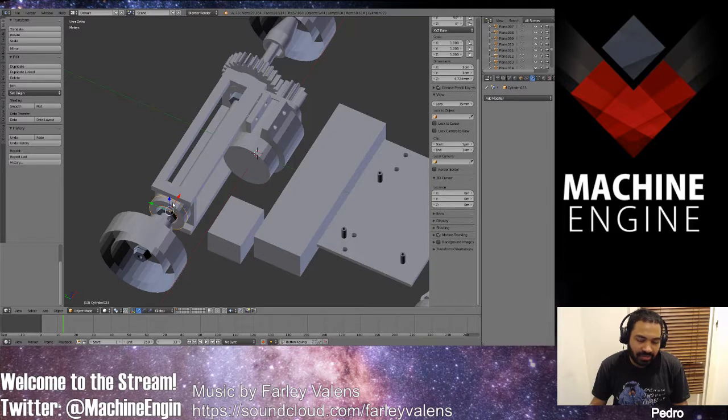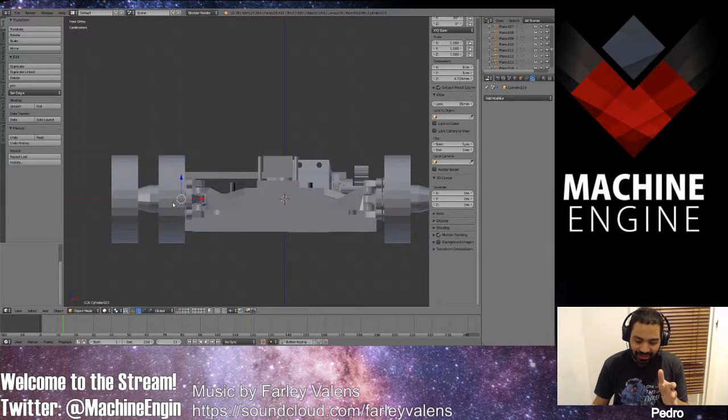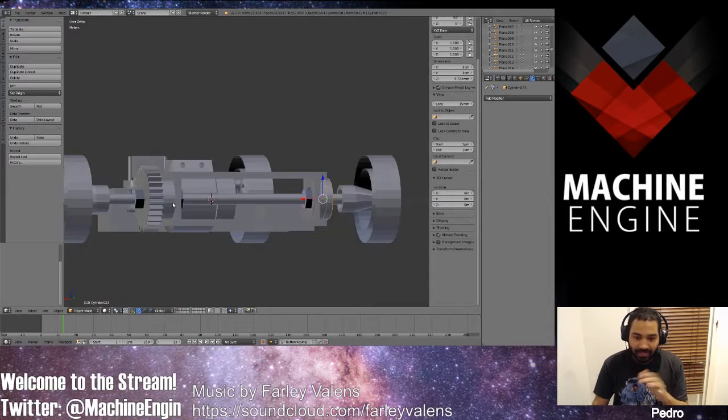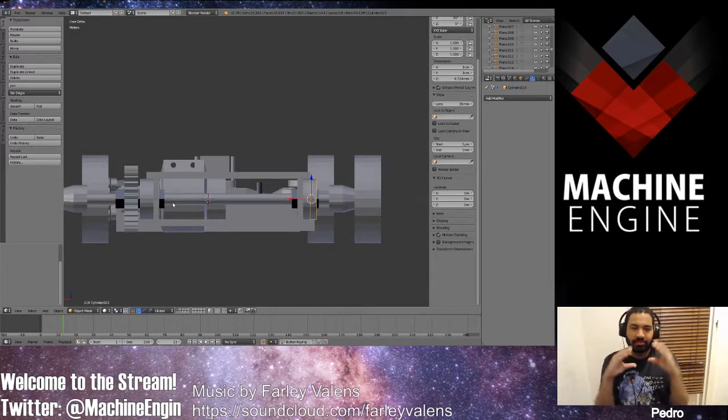So if you print them like they are now, just laying down like this, the circle, because the plastic is still pliable while it's printing, can actually, because of gravity, go down and become a bit oval shaped. So you have to watch out with that.